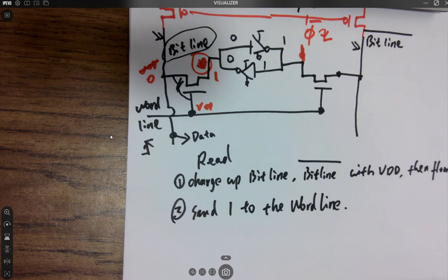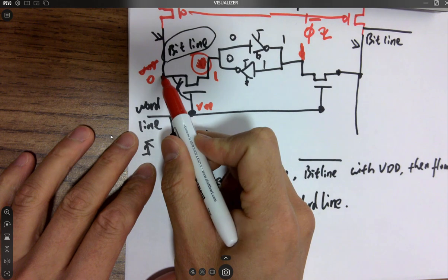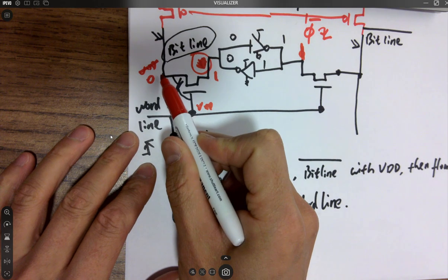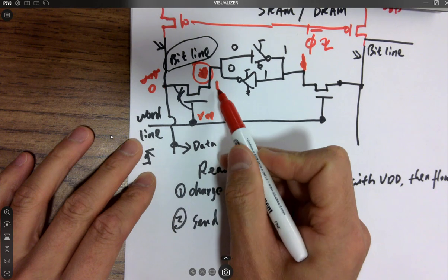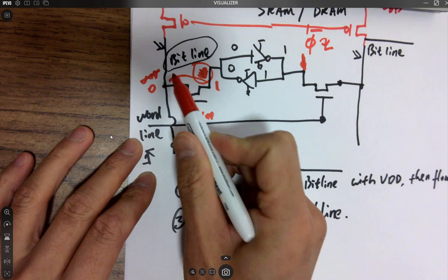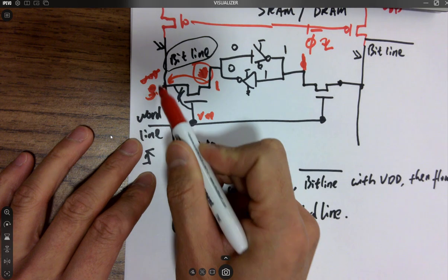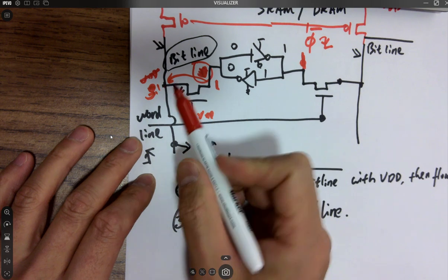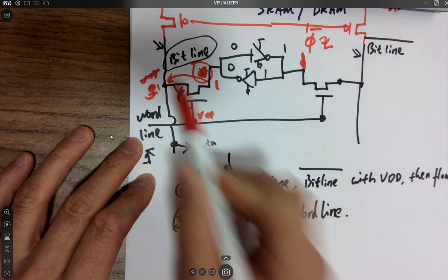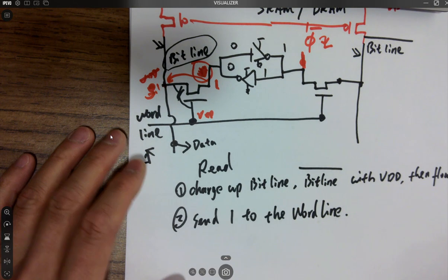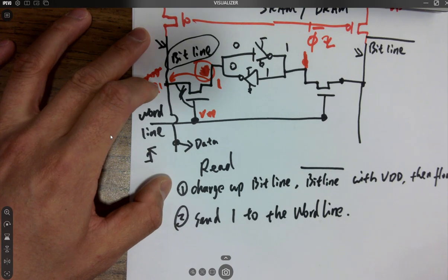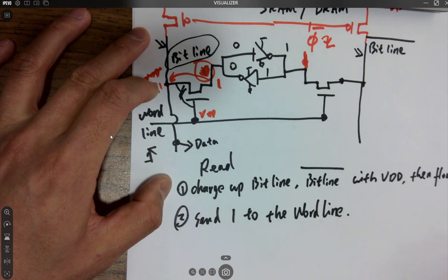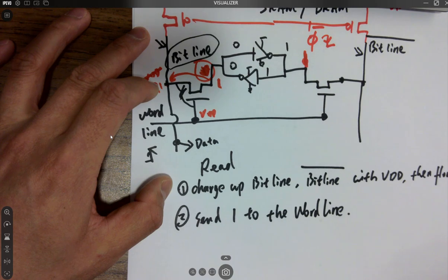So power is probably not that significant a difference, because if you ground it and then shut it off, it's a floating ground, and then if you had a 1 here, it will charge up this point and put it up to 1, and you start reading a 1. My question is, can you really charge this up to 1? We learned it in the past. We covered this a lot. No, it'll be 1 minus VTH. So you are losing a voltage.